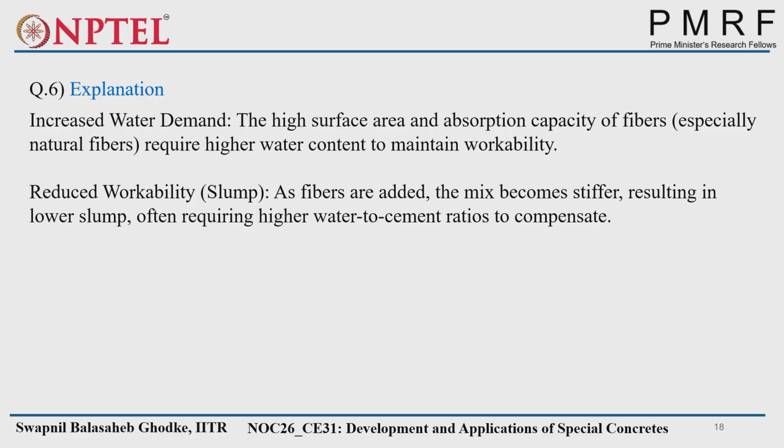So when you are going for the flexural strength, or whenever your beam is under flexure, the cracks will occur less, and because of the fibers, bridging will happen. The widening of the crack will not happen. So that's why tensile capacity goes on increasing.